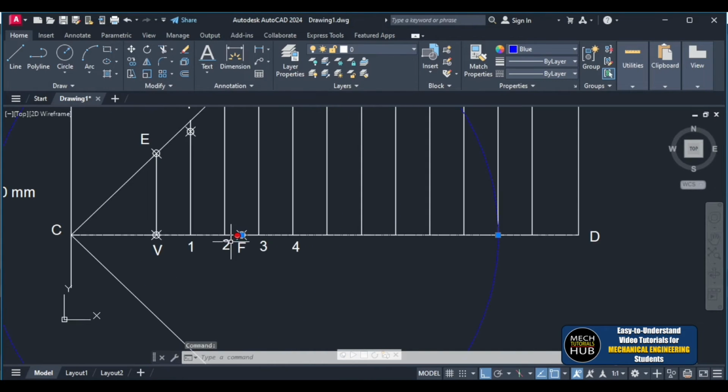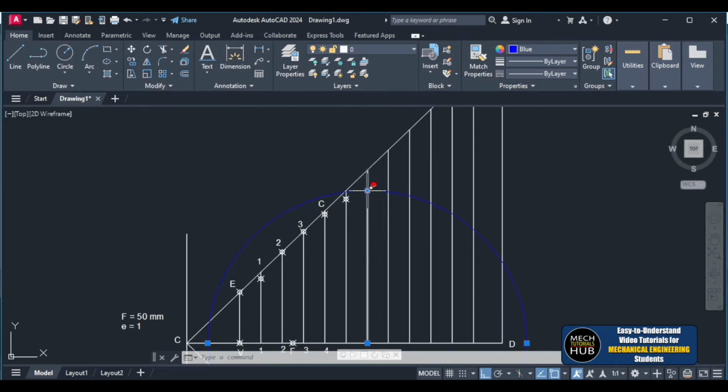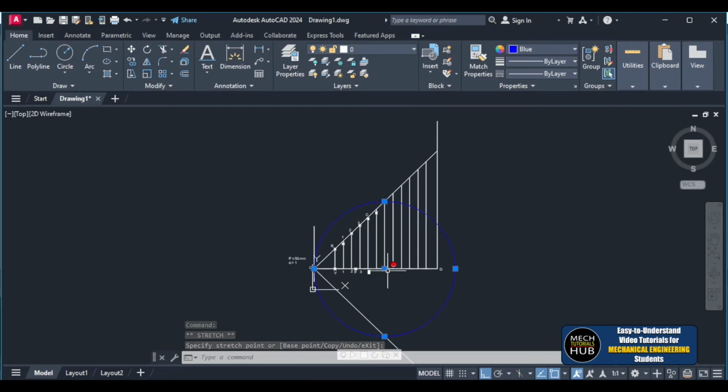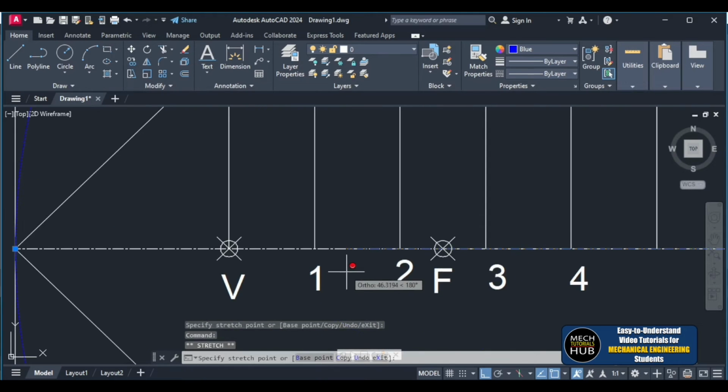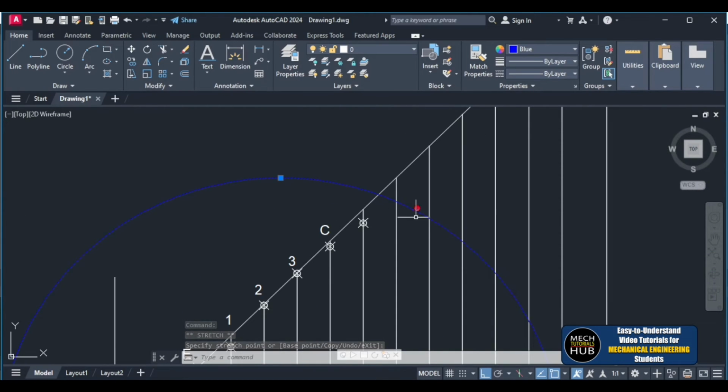Now, if you have watched my previous lecture on the ellipse, after the fourth or fifth point, the intersection slowly comes down, but here it is not happening. The only reason is we took the midpoint as the vertex for the parabola. That is the only reason. So there is no way it is going to come down. Okay, the intersection of 6 6, here is the point, PO, just keep on going up.